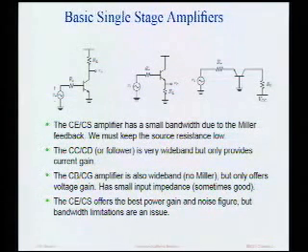How about the common base amplifier shown here? Again, common base amplifier, it's wideband. It doesn't have the same issue with the Miller effect. But it doesn't have any current gain. It only has voltage gain, so it's not going to give us as much power gain as a single stage amplifier. Now, I'm not saying that they're bad amplifiers. They're very useful. They're particularly useful when we use them in conjunction with other amplifiers. In other words, when we have 2 stages or 3 stages, or if we use feedback.